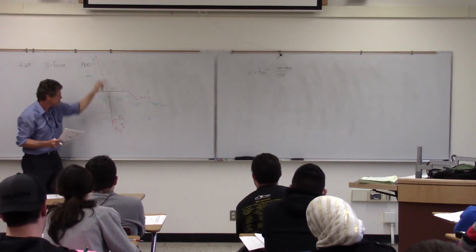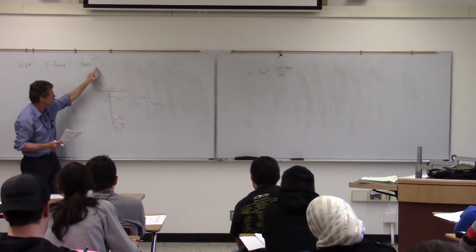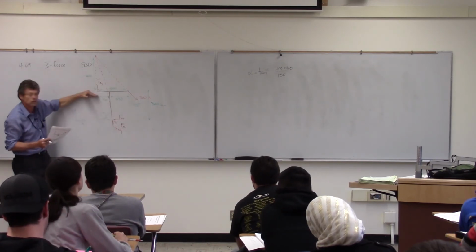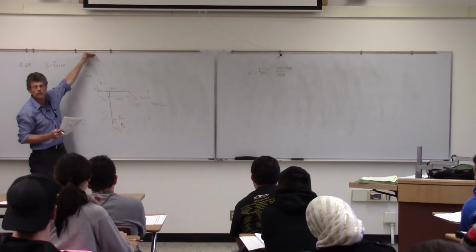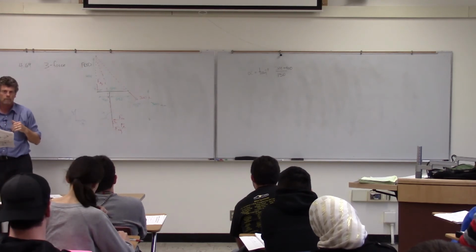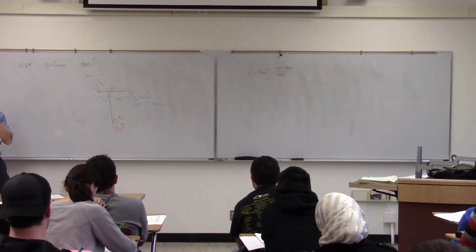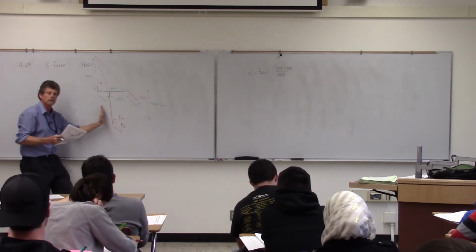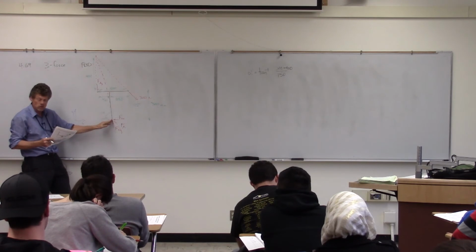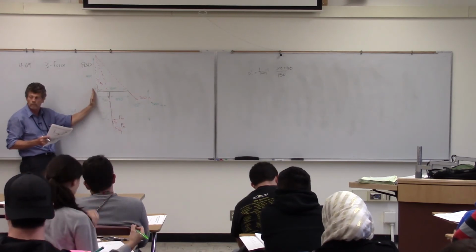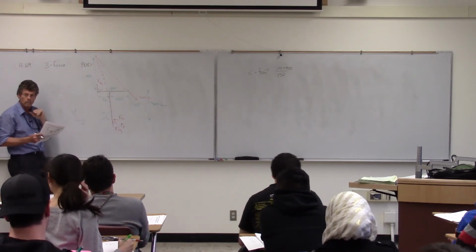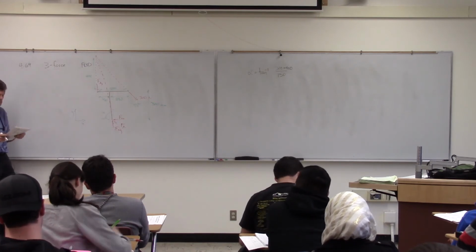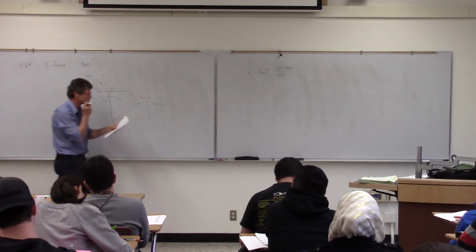So the rise for my angle here has to be 300, which is the height of this structure, plus the 400 to the point of intersection, right? Comfortable with that? I see a lot of heads kind of going, oh. And then my run, since I'm going from C, is only going to be this 150. That making sense? What I'll do is post this solution too so you can go through it.